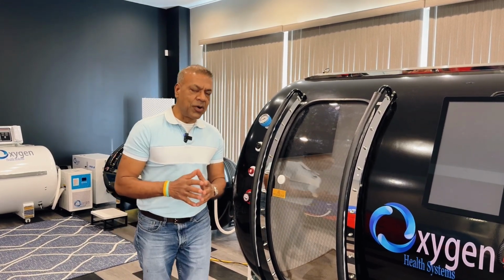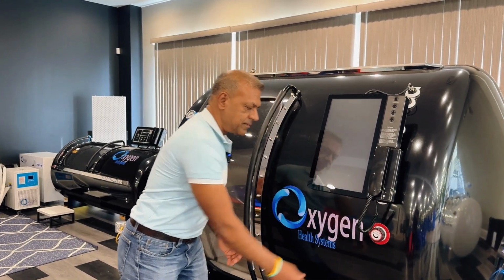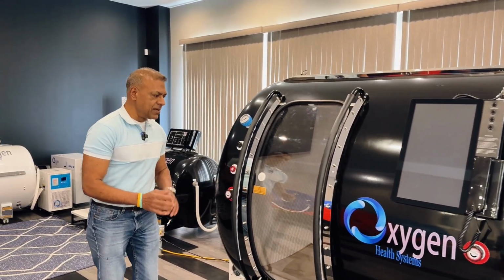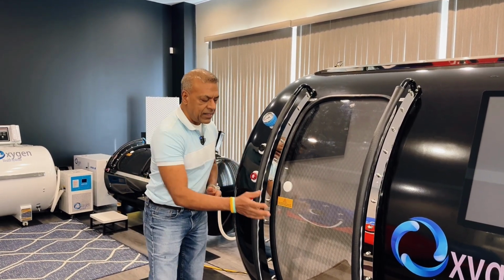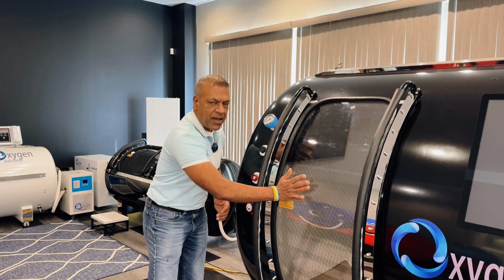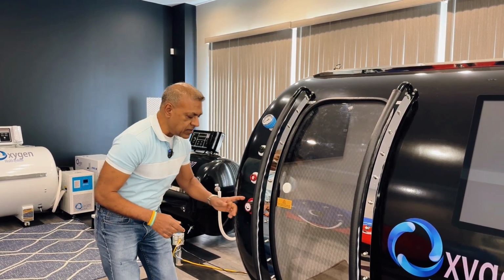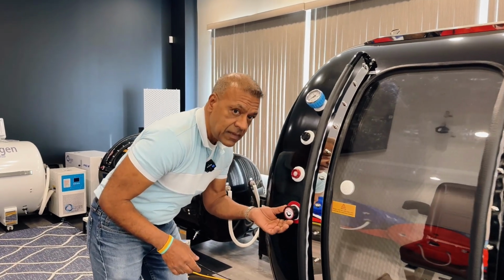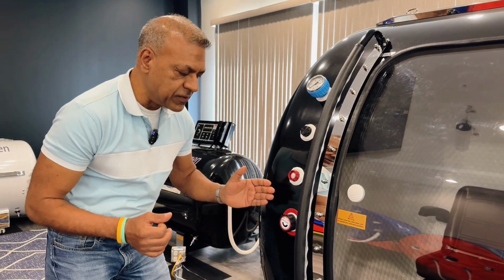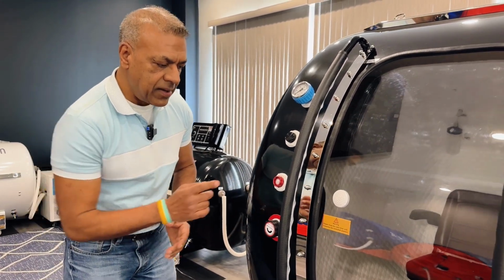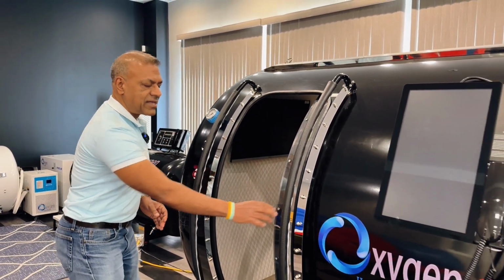Once again, you are only going to be engaging this in the event of an emergency. Once the chamber is brought down to 0 kPa, the door would open automatically and you would be able to open the door. At this time, I cannot, simply because it is under pressure. So here is the air that's escaping, and I'm hearing that the sound is tapering off, and now in just a few seconds, the door would open, such as that. And now you are ready to step out of the chamber in safety.